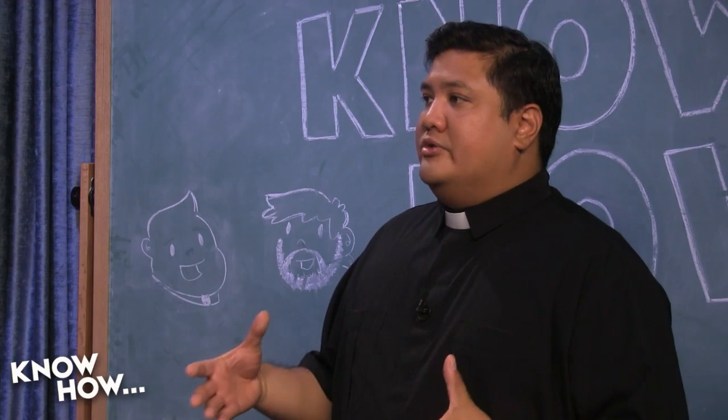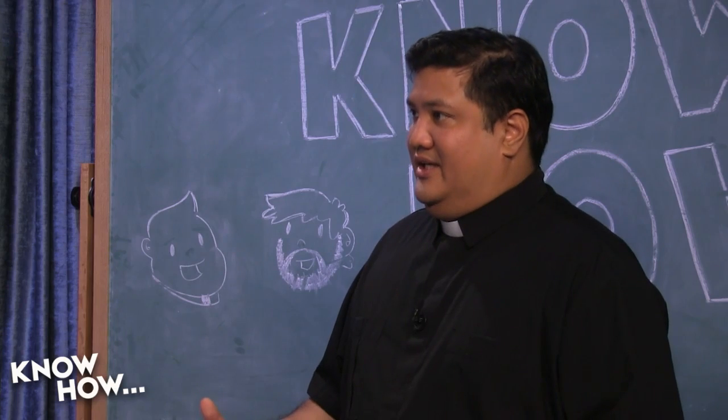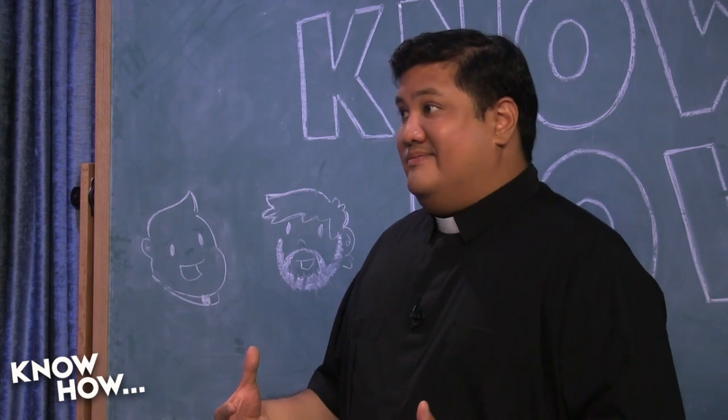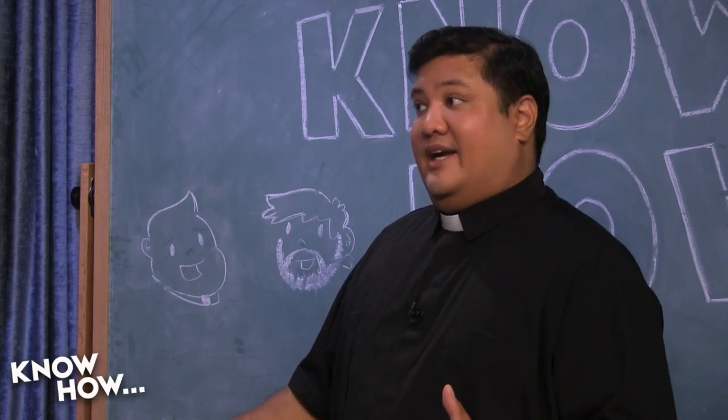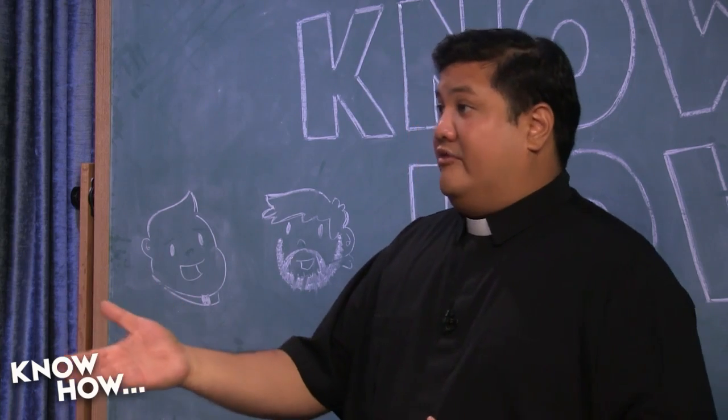I'm not big on using Raspberry Pi for embedded projects because Raspberry Pi still has a file system in it. So if the SD card gets turned off improperly or something like that, it could corrupt the system. Precisely, and it has a long boot time and a long shutdown time. And if you disrupt power and then connect it, there's no guarantee that it's going to come back up the next time, because you may have corrupted the SD card.